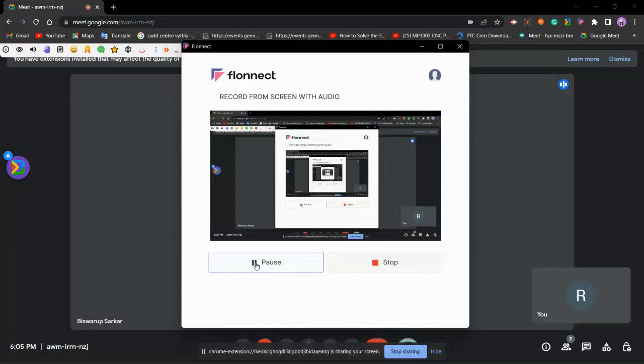For extrude here, what we call is pad. For extrude cut, we call pocket. For revolve, we call shaft. For revolve cut, we call groove. And for sweep, we call rib. And for swept cut, we call slot. For loft, we call multi-section solid. And for loft cut, we call removed multi-section solid.